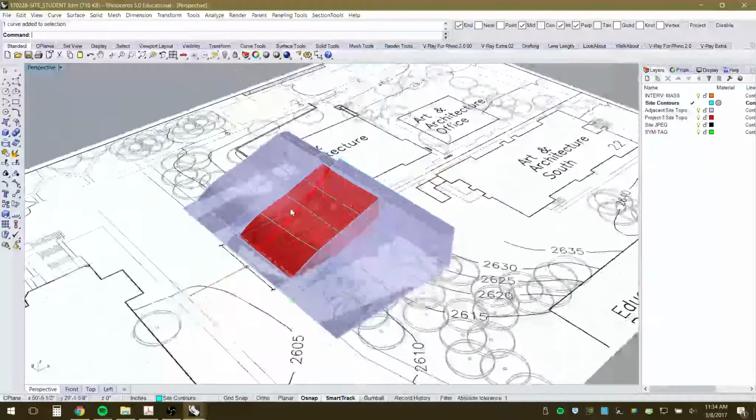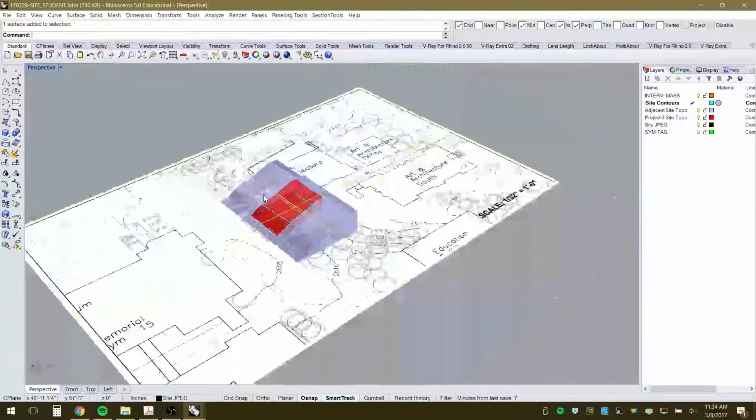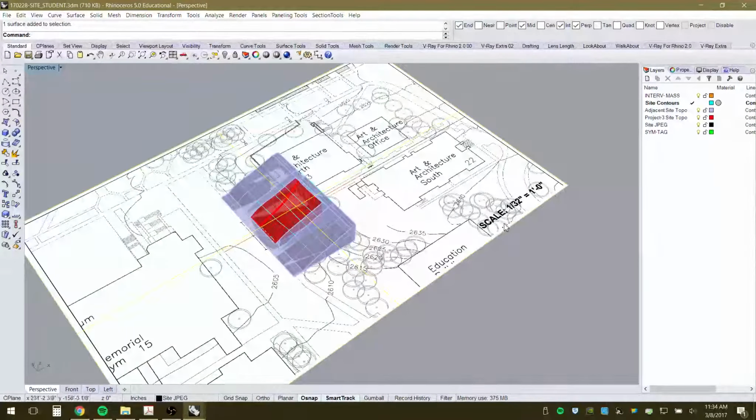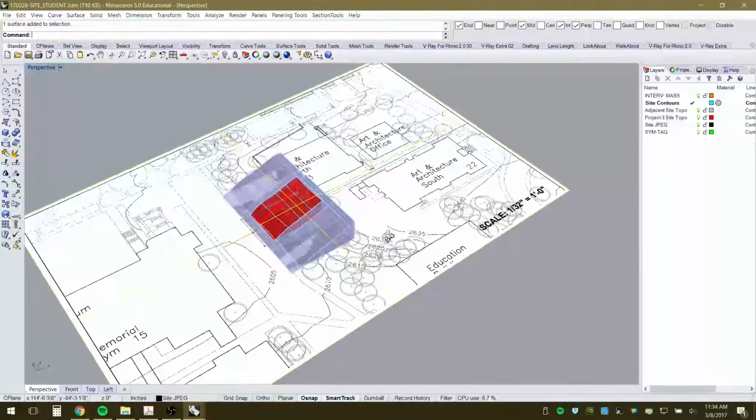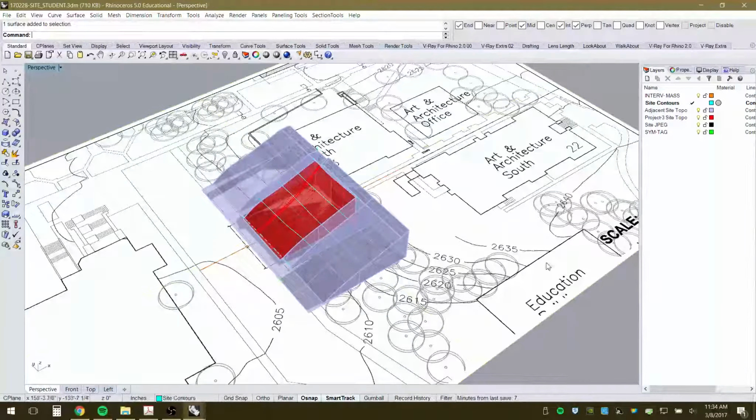Okay, so that's part of it, and then what you'll see on the file are, first of all, I included the overall image. This is the part of the PDFs. You have these available to you for Studio or what have you, so you can use these for analyses and so forth. But I went ahead and brought that in, inserted it into Rhino, so it's placed here to scale, the best I could get it. You know, there's a little bit of variation, but it's pretty close to full one-to-one scale. Now again, when you're drawing using a CAD program, you want to make sure you're drawing one-to-one. You don't want to draw to scale.